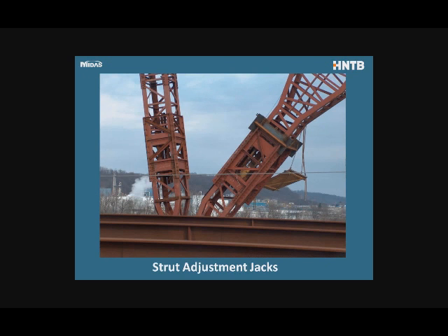The strut system. I have a close-up view of the adjustment jacks, and you can see where they had a jacking mechanism where they could vary the length of these jacks. So this frame just keeps the two parts of the jack together, prevents it from moving naturally. There are four 4-inch diameter threaded rods in there and two large jacks.